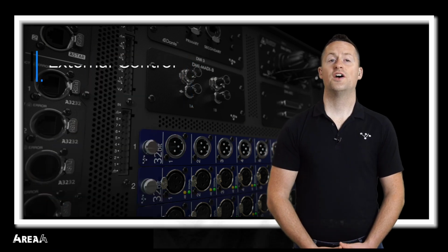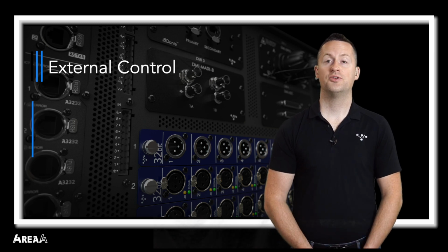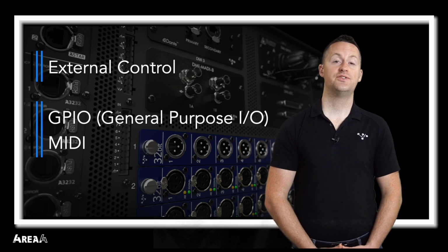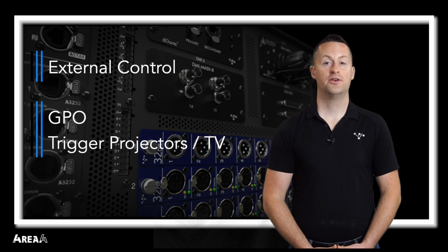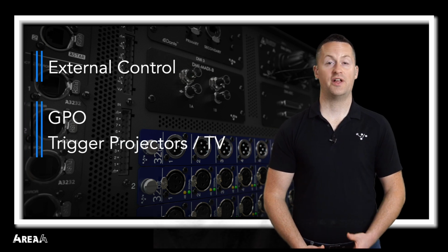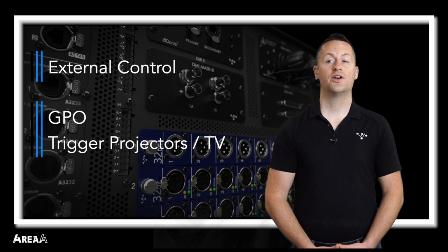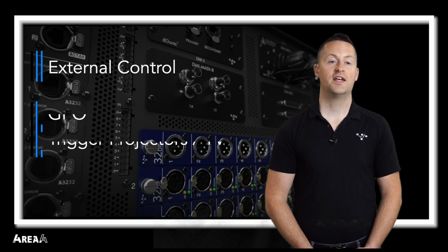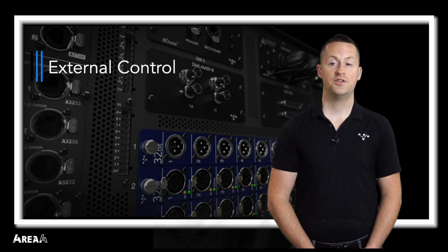The 404 is also capable of firing and receiving GPIO, general purpose input and output, and MIDI messages. Here are some examples of what you could use these for. A GPO could trigger bringing a projector down or turning on TVs, displays, or other scenic elements. This could be a single button to manually trigger, or you could configure it to trigger automatically with the recall of a snapshot.